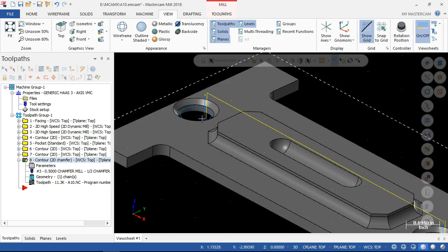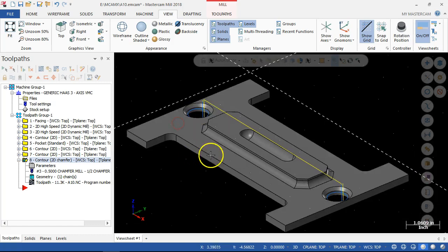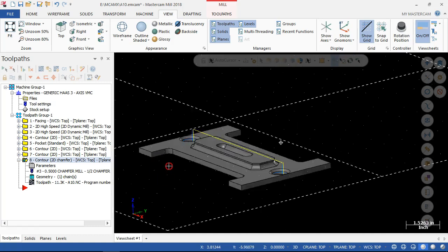Regardless of the operation, I'm probably still going to touch off this chamfer tool and raise it up, I don't know, 20, 30, 50 thousandths. Make a couple of test passes and see what it actually cuts out, how it looks. And then once I've set an actual depth for it, then stay with it. Same with if I was going to do the deburr edge breaks around this of 5 or 10 thousandths, is I would raise it up a little bit, and then in subsequent passes verify that it's giving me the right relief, the right chamfer after we do all of that.